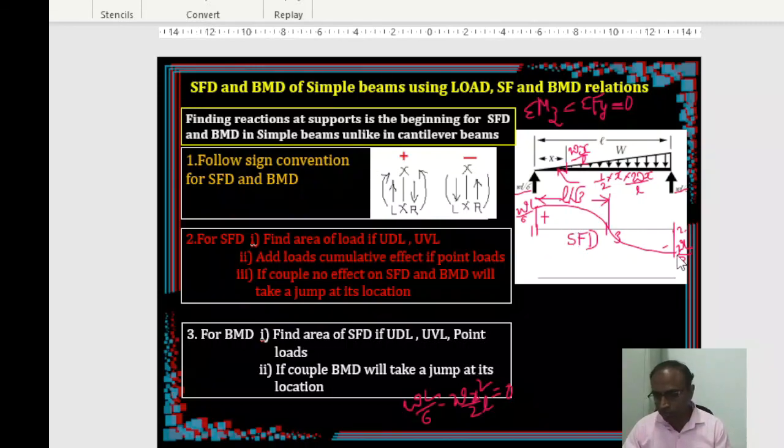So you completed your shear force diagram. Now you move on to the bending moment diagram. In the bending moment diagram, you always know the value of the bending moment at simply supported ends, right? Is there any couple at any end? There is no couple here, there is no couple here, there is no moment. So put 0 here. At roller support and at hinged support, bending moment is always 0. As we told, minimally we are taking 3 points, so if you know one more point, you can construct it. Let's say that point is going to be this one.